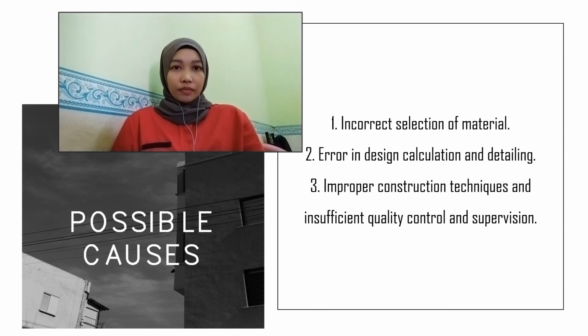Not only does the check need to contain the whole stability of the structure, but also its serviceability and robustness. Regarding detailing, it is the most common factor that results in induced cracks and sometimes failure of the structure. It is suggested to apply correct, robust, and efficient arrangements for the structure. The construction must be built in such a manner that prevents water from staying on the structure and therefore deteriorating the structure.